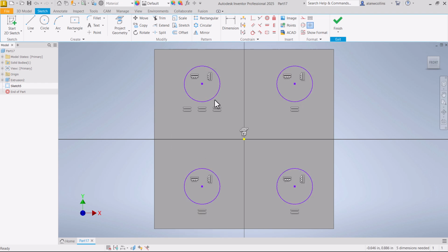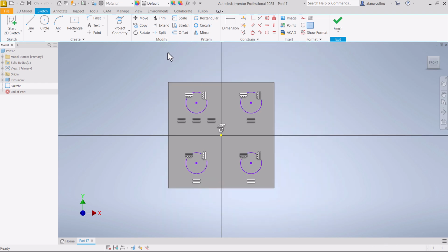The first one that I selected, it gets all of the constraints. It is constrained to, there is the one on the top right, there's the one on the bottom right, and there is the one on the bottom left. It does not create one big collective equal constraint for all of them. It constrains all of them back to the first one that you created.